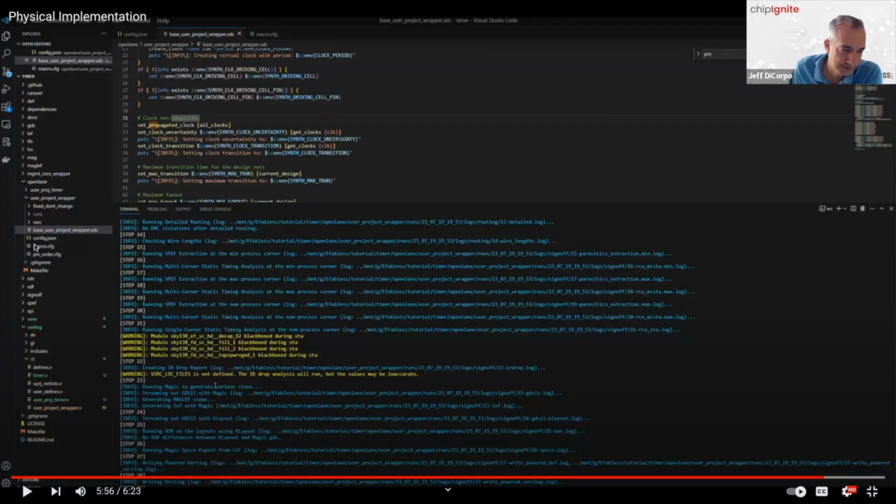configuration file. So there's a config.json file. First of all, let's start in your project group. There's an OpenLane directory. That's where all the configuration information is. There's going to be one subdirectory for each macro that you need to harden within your design. There's going to be one macro called user project wrapper, which is the top level macro that gets integrated into Caravel. That has to be named user project wrapper. You can't change the name of that.